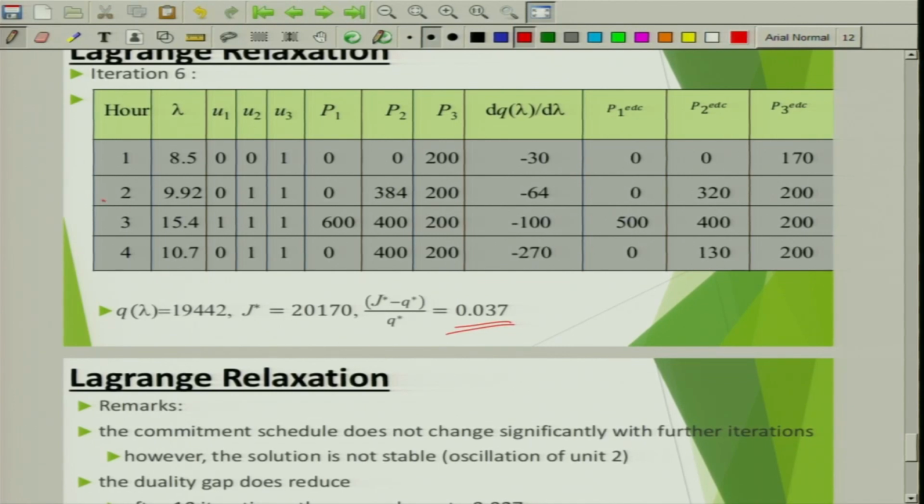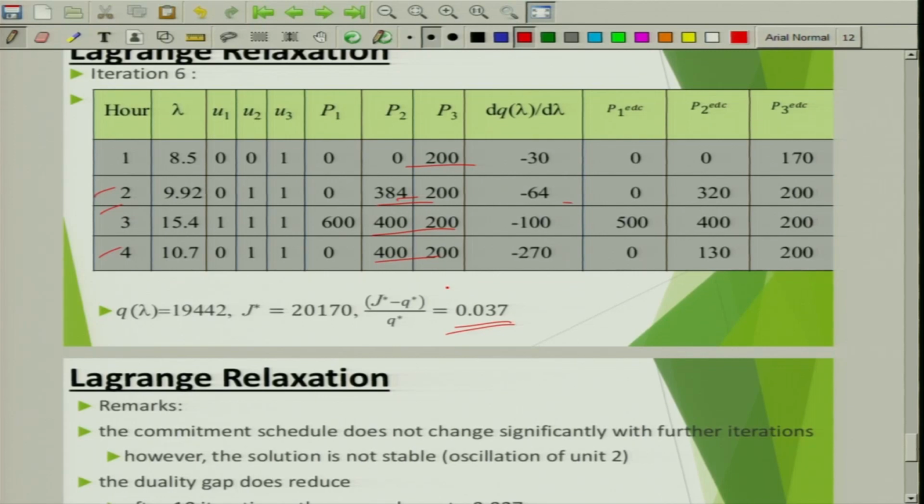and you get the values turning up so that the load demand is met over a period of time, because you are increasing the lambda. Increasing the lambda means you are increasing the generation. So at every interval you get the generation which will meet the load demand. So gradually you would obtain the set of generation. This is the most optimized generation for all the time intervals.